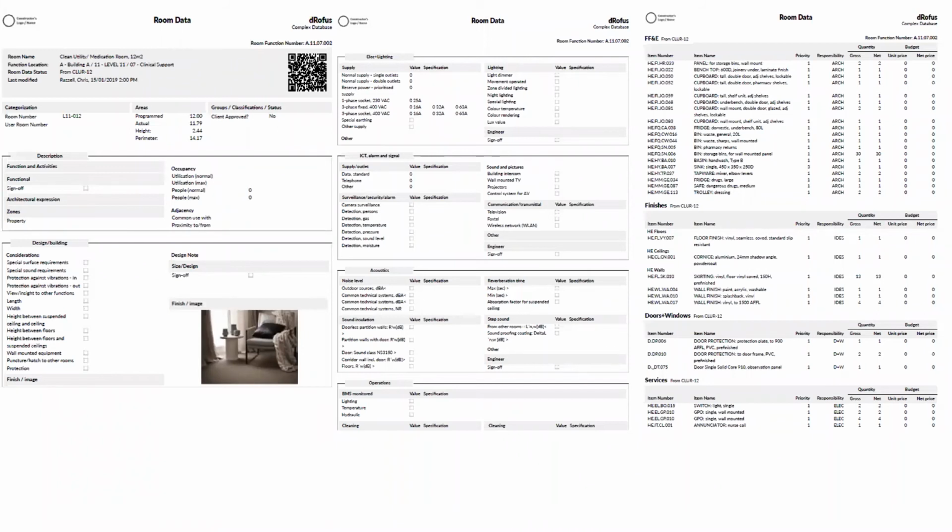Let's say there's MEP models in ours, so we can still generate everything from our model, instead of going through each Revit model to generate. You probably will need to do a sync from the MEP model to get its data into dRofus, and subsequently that will be the sync to do. Because the way the synchronizing works is it needs to have the room inside with the Revit families and Revit content, so it detects that relationship.